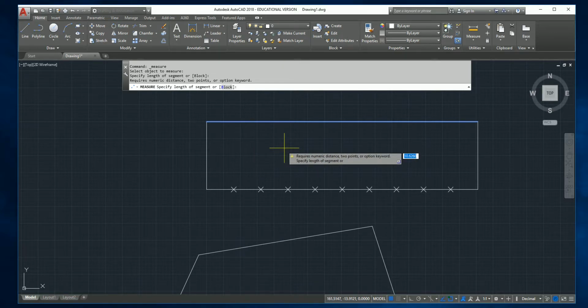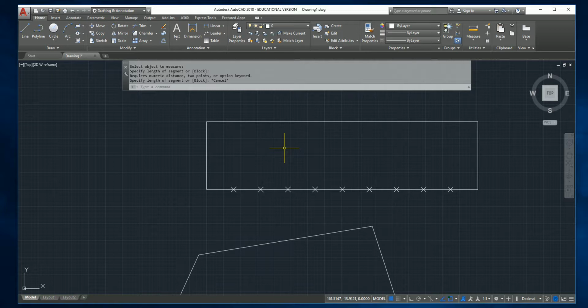So we select object to divide. Selected. It comes up, enter the number of segments. 10. And you have 10 segments that are exactly the same size. Okay, and what's the next key though? Do I click on it? No, you can see. Enter.